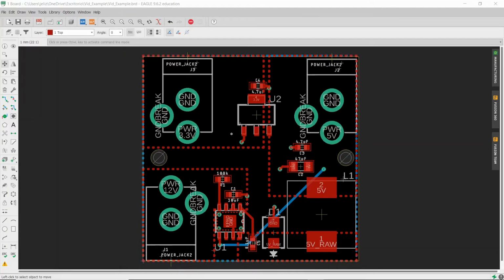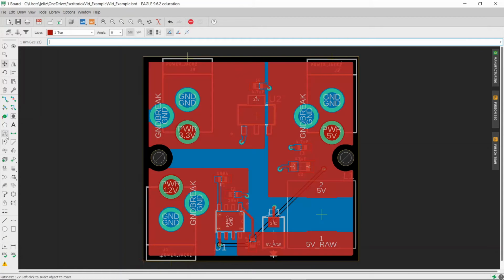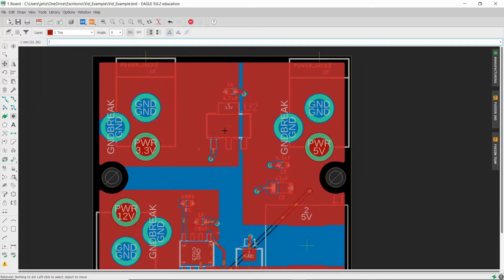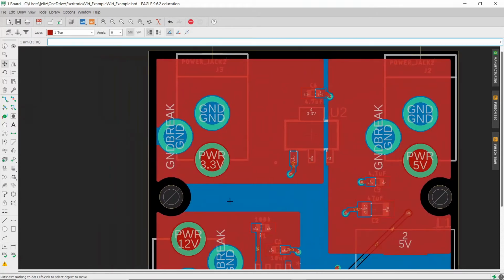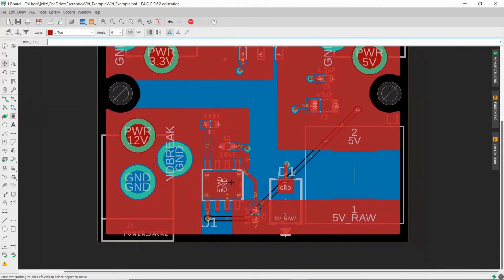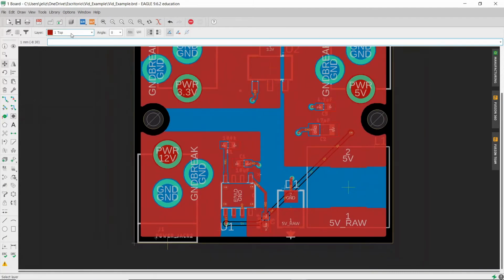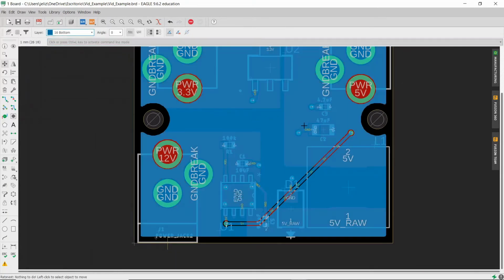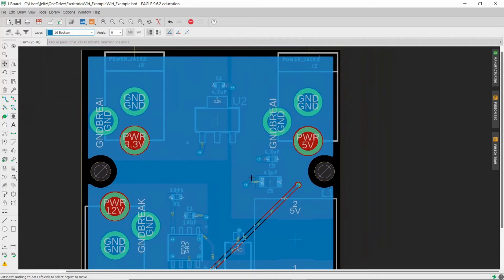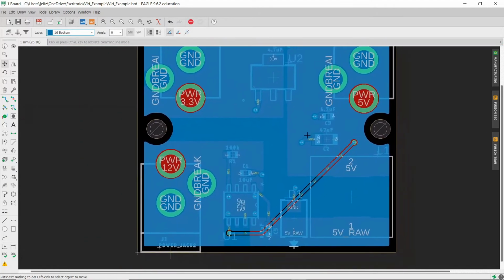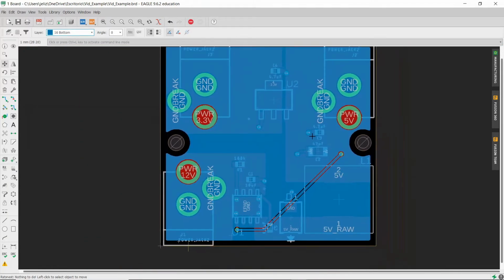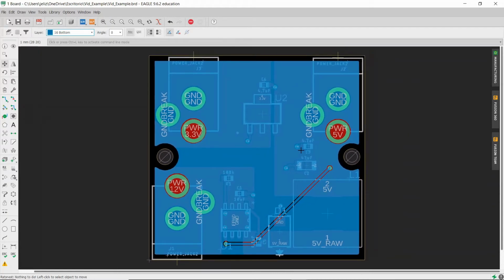Another important tool for multi-layer boards is the polygon tool. When using polygons, the unused copper on the inside of the polygon is not etched away and is instead used as part of the circuit. For a two-layer board, we typically specify the bottom layer as the ground plane. Using a ground plane is important because it makes sure all the components connected to it have the same ground voltage, minimizing interference and ground loops from other parts of the circuit. Ground pins on a device should each be directly connected to the ground plane.